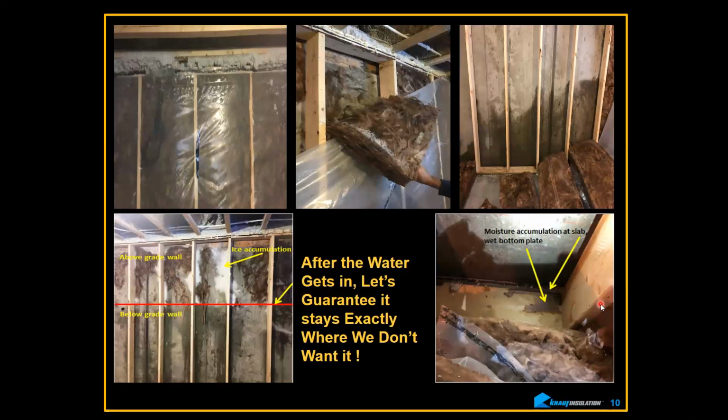So we talked about this foundation stuff. Here's a basement. This is up in Canada. I was up there a little over a year ago. What they did was the classic thing. They love to do this in Canada. They love to use plastic on the walls. It's really because there's very little understanding that you could have an air barrier that's permeable. So plastic is considered an impermeable air barrier. It's definitely a class 1, that's between 0 and 1 perms.